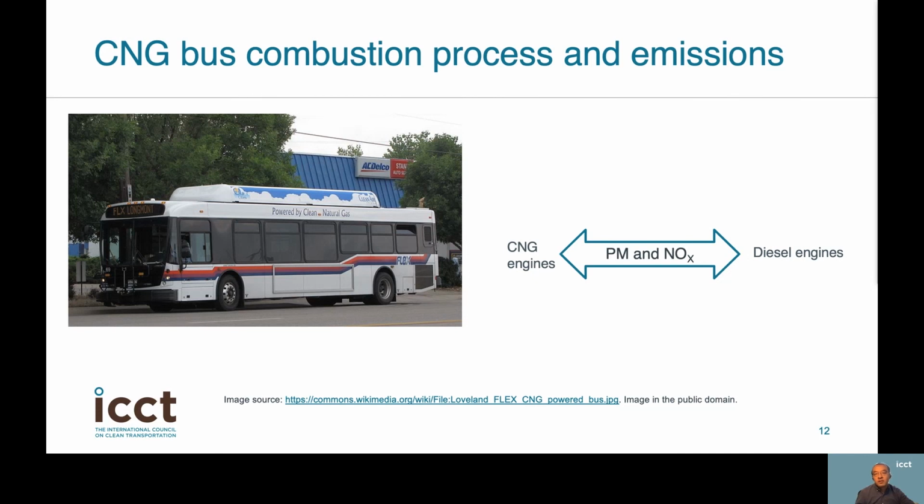That said, CNG buses have higher levels of particulate number emissions than diesel buses. The oxidation catalyst for CNG buses oxidizes the organic fraction of the particulate matter, and this increases the particulate number size distribution emissions. With most state-of-the-art emission control technologies, Euro 6 CNG buses meet the definition of soot-free. Some operators choose to retrofit existing diesel buses to CNG to save costs. It's important to bear in mind that CNG buses need dedicated storage and refueling infrastructure.